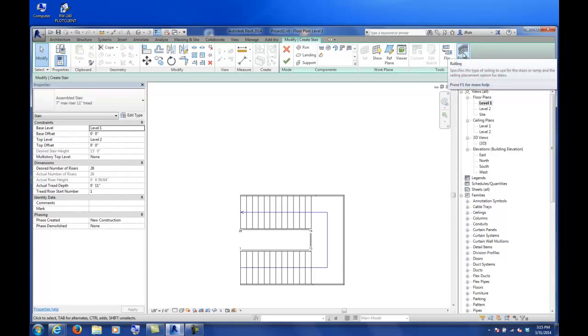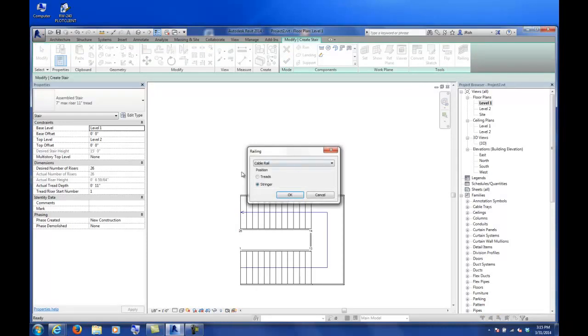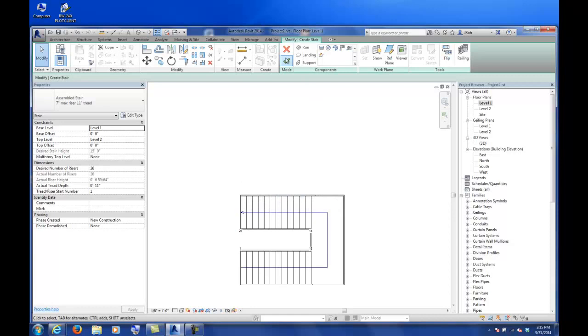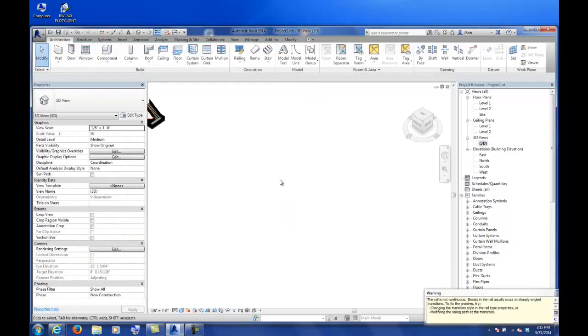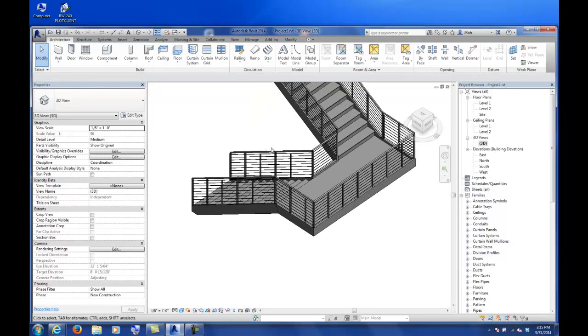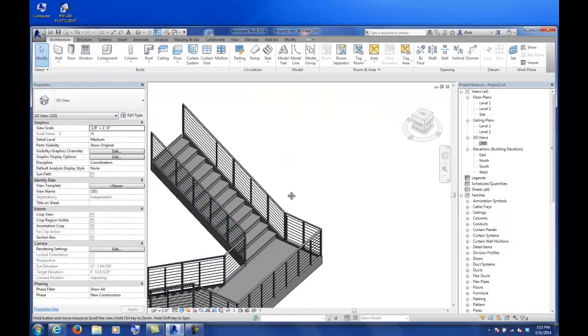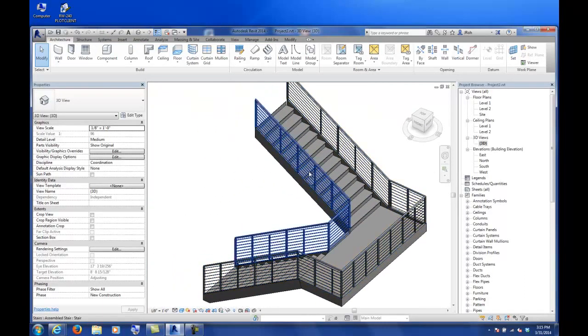All you have to do is set the parameter there where it says cable rail and put it on the stringer. Click OK, and when you hit the checkbox to close out of this, it'll generate the stair with that railing on it. So you can see there if you look at it in 3D once you've placed it. You need to hit the...